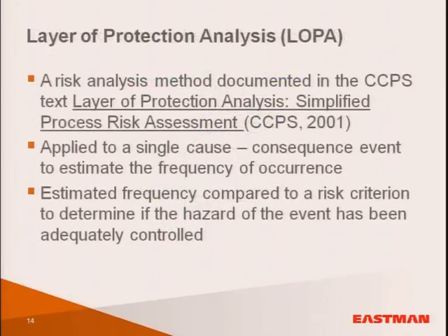So in order to determine what the reliability of the instrumented protective system needed to be, I performed a layers of protection analysis. And we've talked about this throughout the entire session. So we basically just looked at our single cause consequence events and looked at the frequency of occurrence and determined if the hazard could be adequately controlled by the instrumented protective system.